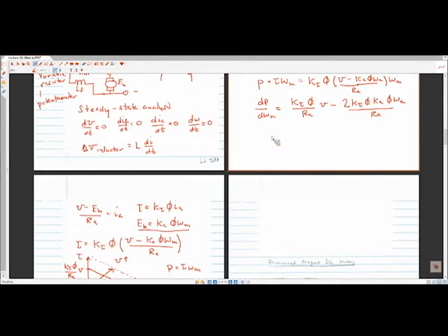We'd have to solve this for 0. Please be checking my math as we go through here. Ra cancels, one of these phi's cancels, tau cancels, and so you get V over 2 Ka phi equals omega m, we'll call this peak. As a first pass. Did I mess up something?